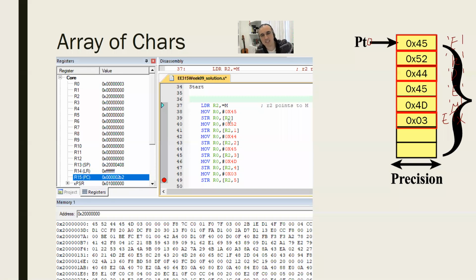There is something not quite correct with this code, guys. Can anybody correct me? Look at this instruction. Any ideas? No? Guys, I'm writing only a single byte, but I'm using the instruction str. So does it sound correct to you? Or what else could it be? Any ideas?